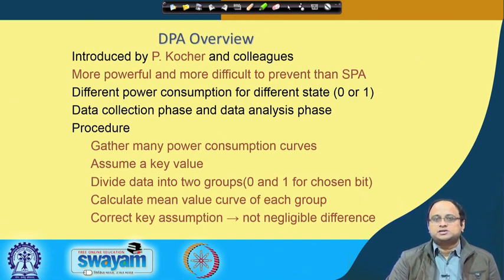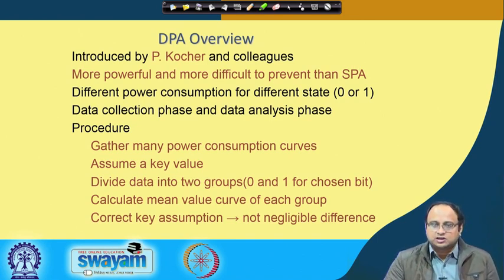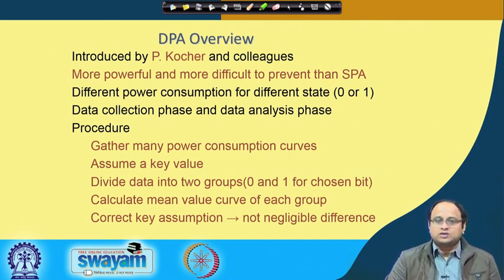Okay, if we simplify even further, let us consider an inverter, for example, a CMOS inverter. Whether you are operating on 0 as an input or on 1 as an input, your power consumption will vary. Okay, and since it varies, you find out that the power consumption depends upon the underlying data in our normal technology, and that is exactly what is being exploited in these attacks.